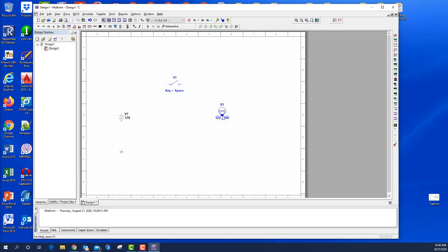Be careful when you're clicking on components. Sometimes you can just click on not the entire component, but just the text or the label that goes with the component. See that? I'm just clicking on the labels, and that's not going to move the component. When you click on text, you'll get the four corners. When you click on a component, you get a dotted line box around all of it, and that's what you want to get to move that entire component.